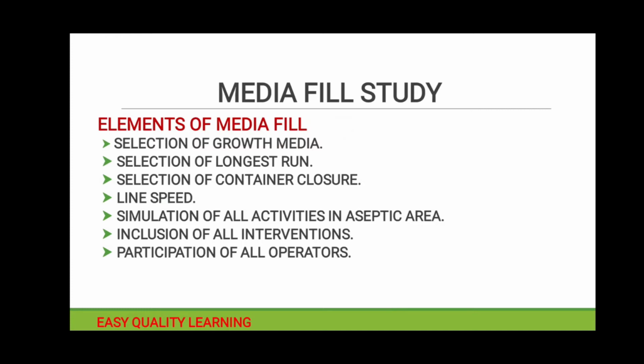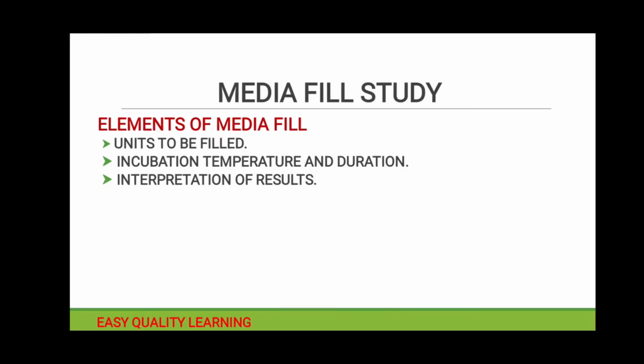So: selection of growth media, selection of longest run, selection of container closure system, line speed, simulation of all the activities in aseptic area, inclusion of all interventions, participation of all operators, number of units to be filled, incubation temperature and duration, and interpretation of the results. All of these are subparts of the media fill activity which need to be taken care of when we are making a protocol and whenever we are deciding on the media fill activity. So let us understand these things one by one.